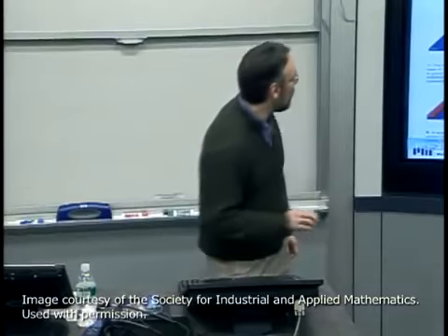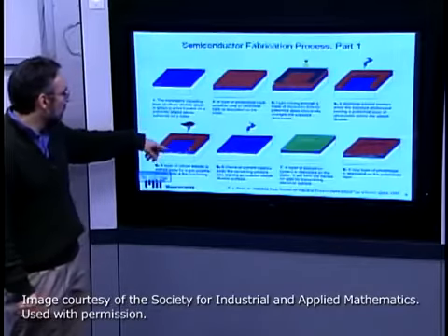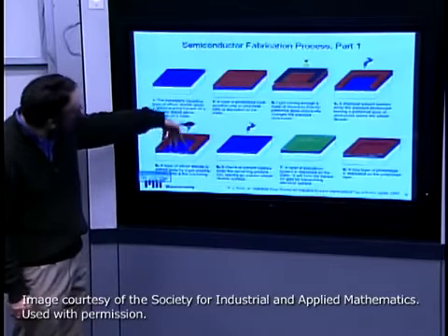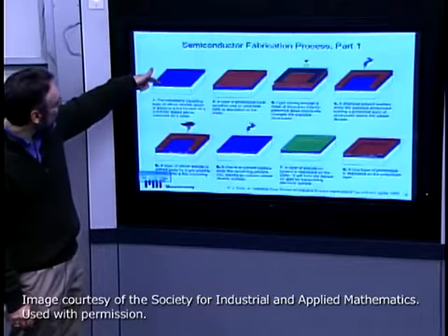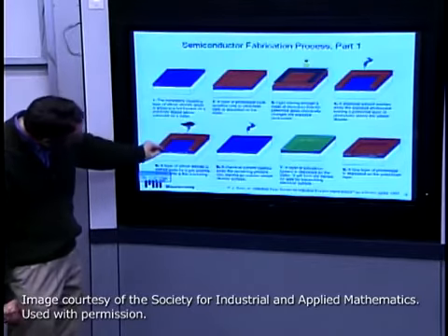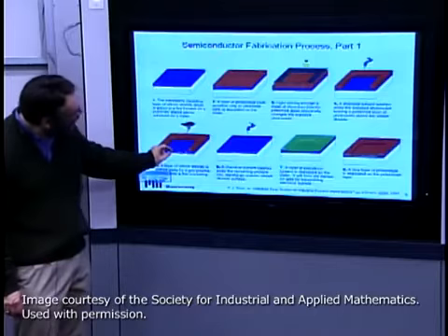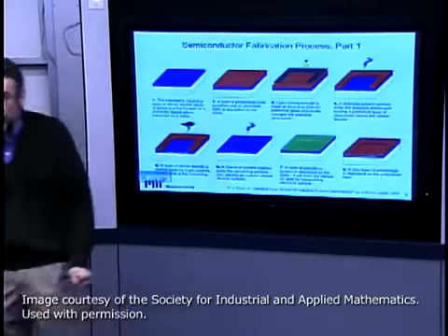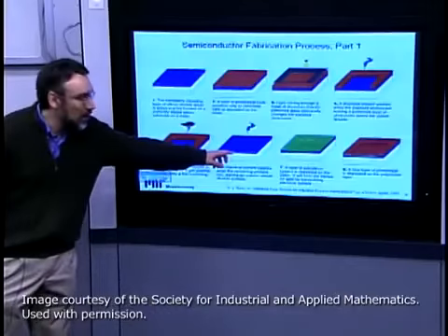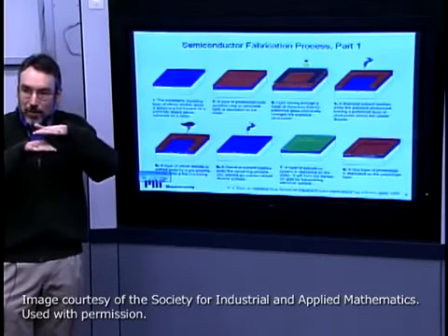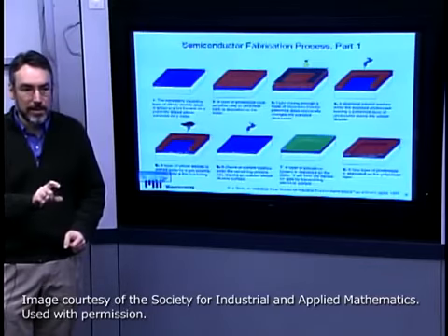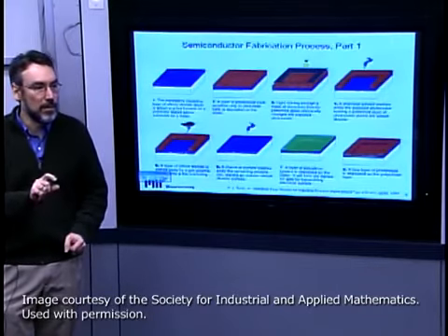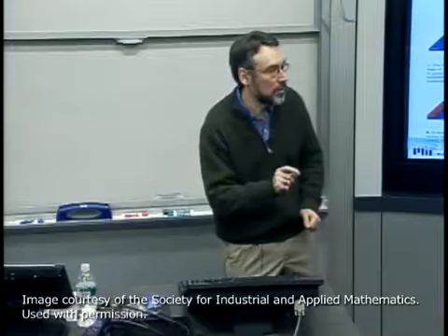Now in this picture, what they're trying to do here is show that we are partially etching some silicon dioxide layer away, apparently leaving a small remaining level or layer of silicon dioxide. So you can sort of see that shadowed down in there. What they're trying to show in this case is they're leaving this thin silicon dioxide layer that is going to be that insulator between the gate electrode and the silicon that we talked about in the final structure.